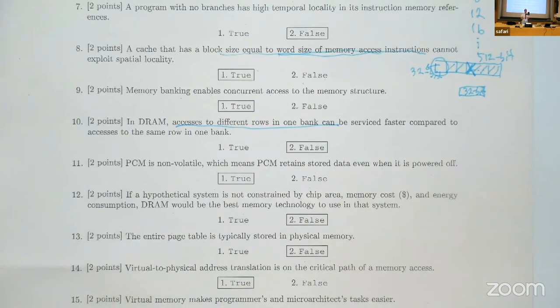That means you have a row enabled. Basically, this access pattern will have a lot of row conflicts or bank conflicts. This means that you enable a row, you spend some time to satisfy the latencies, the timing parameters, and then you precharge that row, you enable another row, you precharge it, enable another. It's like a double-sided RowHammer attack, if you remember that.